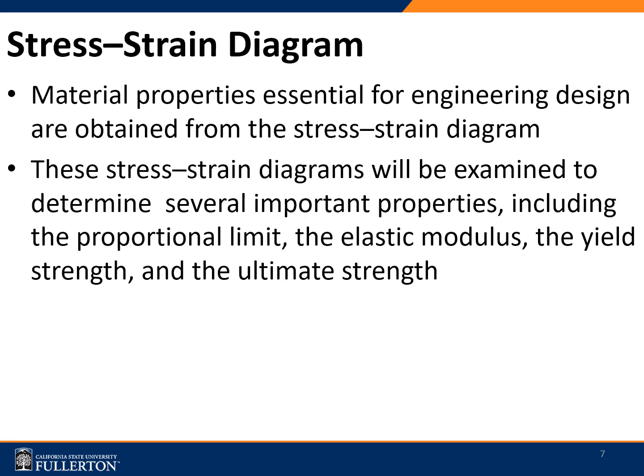What we get from the stress-strain diagram is a very useful engineering tool that could explain or give information about the material properties as well as the behavior of the material. We could gather information including the elastic modulus, the yield strength, the ultimate tensile strength, which are extremely useful for engineering calculation purposes.